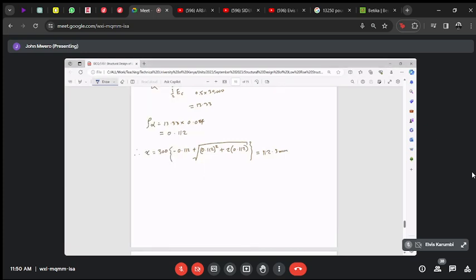And I keep deviating from the calculation so that you can understand where these equations are coming from and why we are even bothering to calculate that. For example, we spent a few minutes on why we need to calculate the value of x, the depth of the neutral axis, because the material is not perfectly elastic and not perfectly isotropic. So now I want to find the stress in the tensile reinforcement steel.